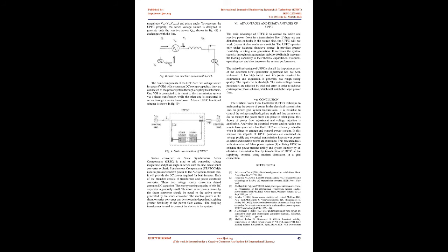Combined series controller. This is the combination of separate series controllers. They are controlled in a coordinated manner in a multi-line transmission system. This could be a UPFC in which the series controllers provide independent series reactive compensation for each line and also transfer real power among the lines via the power link, as shown in Fig. 5.